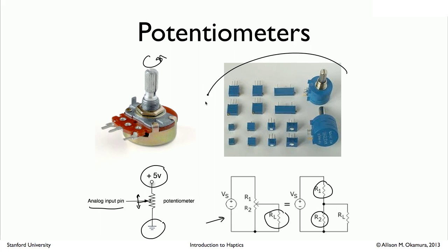These are examples of a bunch of different potentiometers and what they look like. If you were going to use a potentiometer as a rotation sensor for a haptic device, you would typically use something that has an actual knob on it like this so that you can attach to it. One word of caution on using a potentiometer with a haptic device is that because the way in which it works is by dragging a pin along a physical resistor, it has some inherent friction to it.